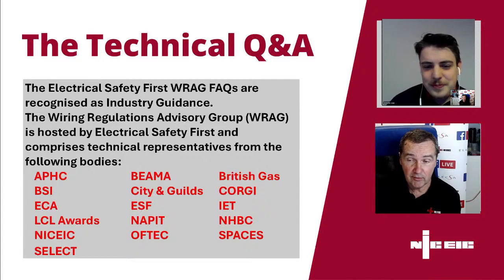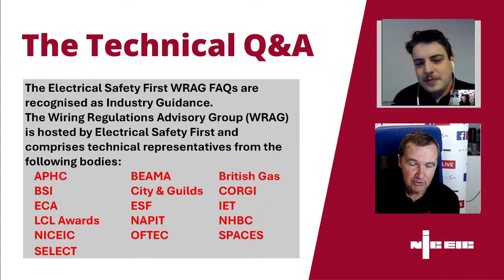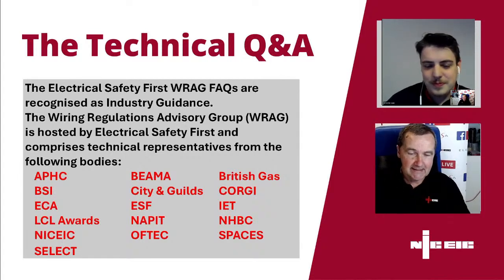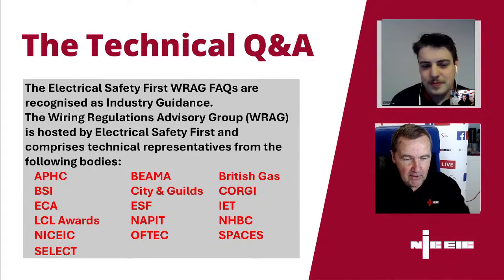Yeah, really true. If, for example, that's your point of isolation, then that should be readily available, so it shouldn't get covered by food tins. And likewise, if there is a functional switch in there, the last thing you want is somebody putting something into that cupboard, inadvertently operating that switch. So yeah, a good point that you should really think about what it's being used for.